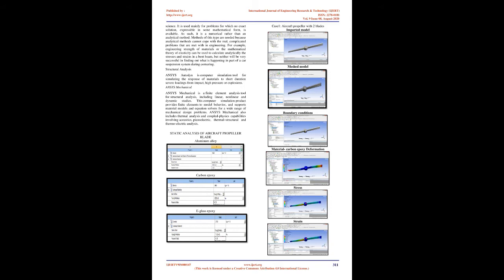In addition to creating solid models and assemblies, CATIA also provides generating orthographic, section, auxiliary, isometric or detailed 2D drawing views. It is also possible to generate model dimensions and create reference dimensions in the drawing views. The bidirectionally associative property of CATIA ensures that the modifications made in the model are reflected in the drawing views and vice versa.